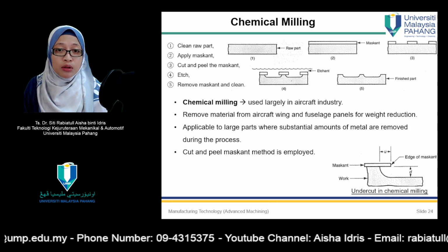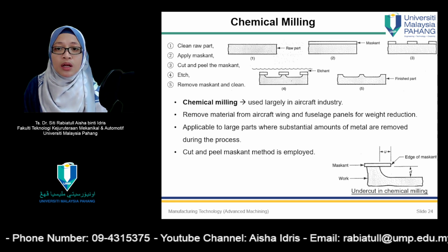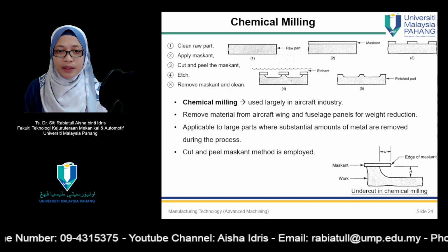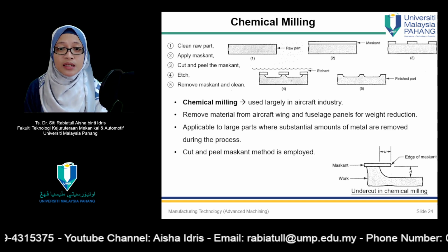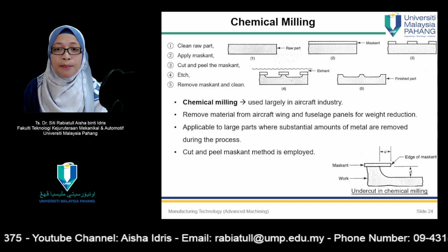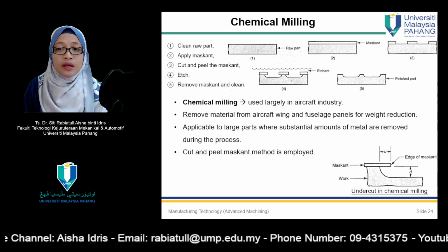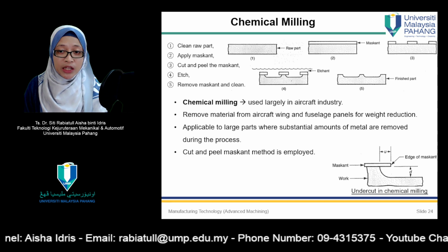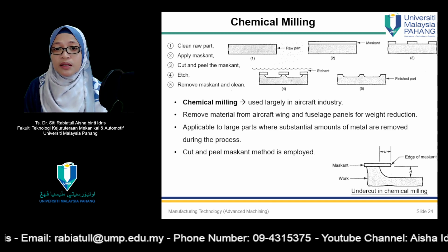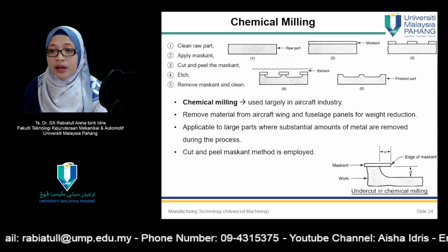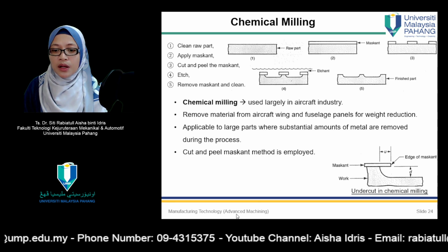It is applicable to large parts where substantial amounts of metal are removed during the process. The cut and peel masking method is employed. A template is generally used that takes into account the undercut that will result during etching. And the sequence of process steps is illustrated in the figure here.